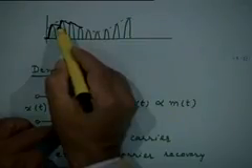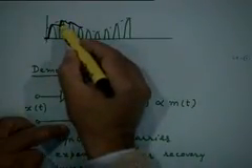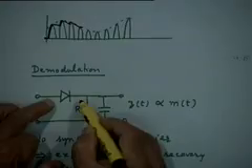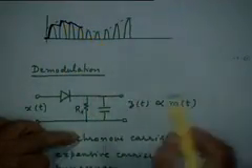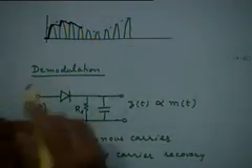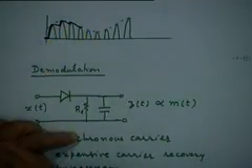We don't want the discharging to be too fast, so that it more or less stays at the constant value that it had charged to, except that it decays just a little bit, right? And then the next half cycle comes in. At this point again the diode becomes forward biased, again the capacitor starts charging, it charges to the new peak value, and this cycle of operation repeats itself to produce an output waveform which looks like the black profile I have shown here, right?